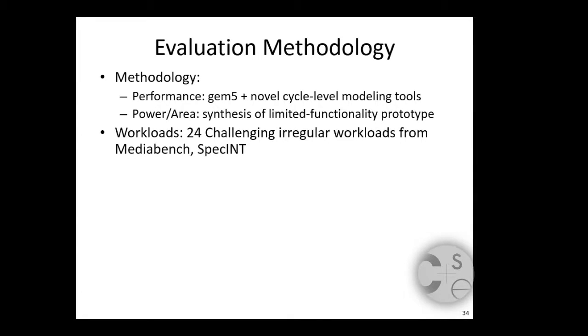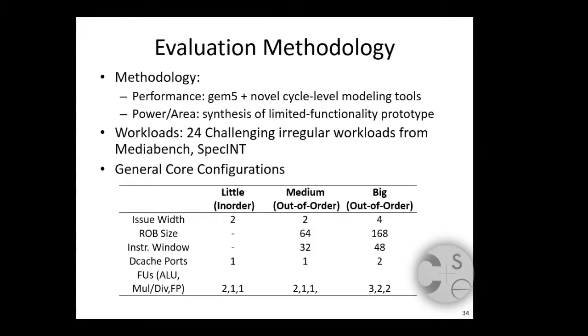So finally, I want to talk about some results. The way that I study this architecture is by developing a novel cycle-level modeling tool, which I'll be happy to talk to you about after the talk. The workloads that we chose were irregular workloads from MediaBench and SPECint, because they're very challenging to improve. And I'm going to explore adding the Dataflow architecture to a variety of different general-purpose cores, including a small in-order core, all the way up to a much larger out-of-order core.